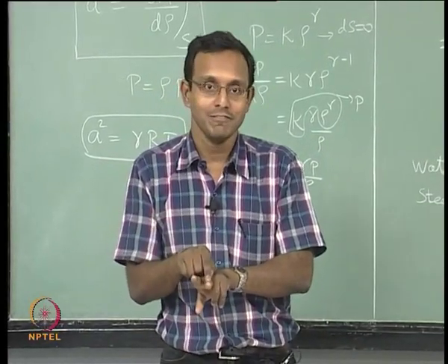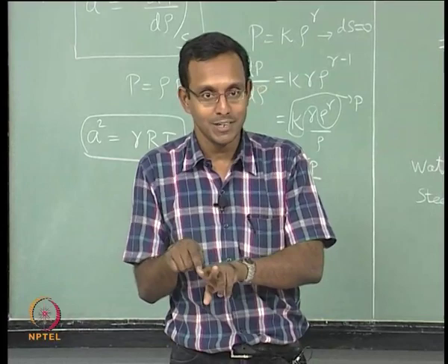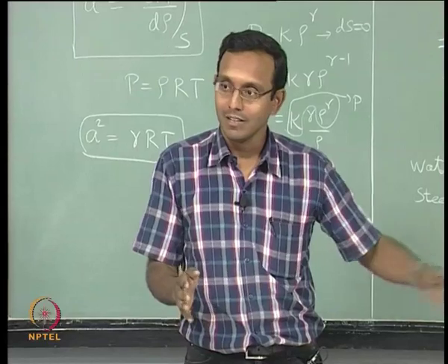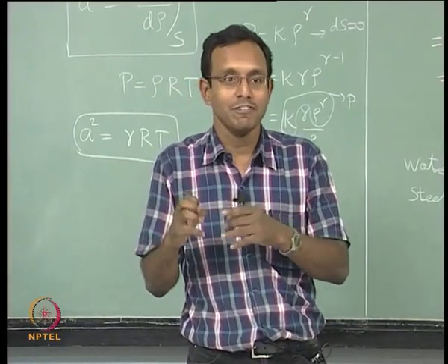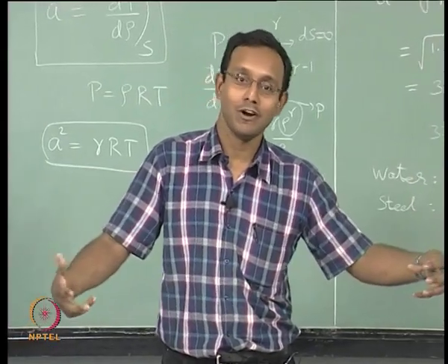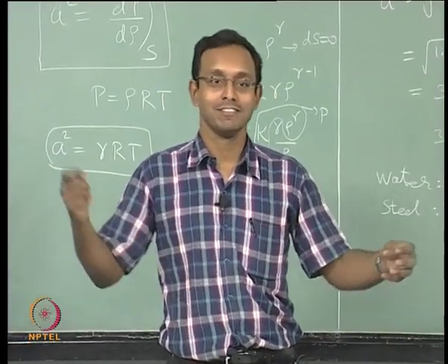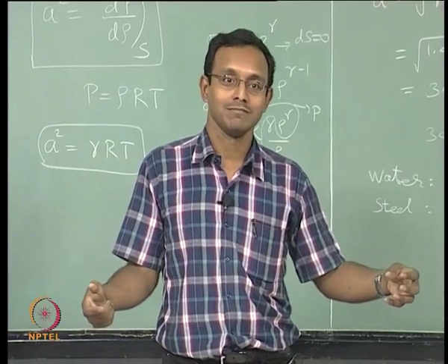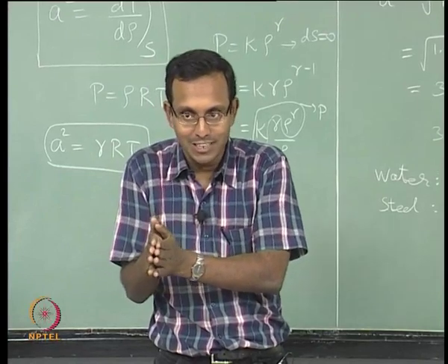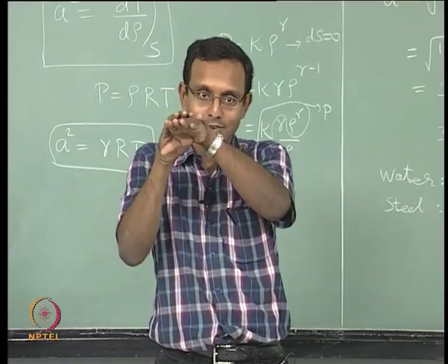One is a compression wave which is telling the pressure or the stress has been increased in this medium, and the other one is telling stress has decreased. Okay. So now these two are going. If it is not very strong pressure pulses, then there is no material damage to this steel rod. Let us say I am just wanting to hit it slightly, say I took a wood hammer and hit it with a metal thing, nothing happens to the steel most likely. So if that is the case, then it will have some stress and then it will relieve back to original position. So what really happened is the stress went up some value and came back the same amount.